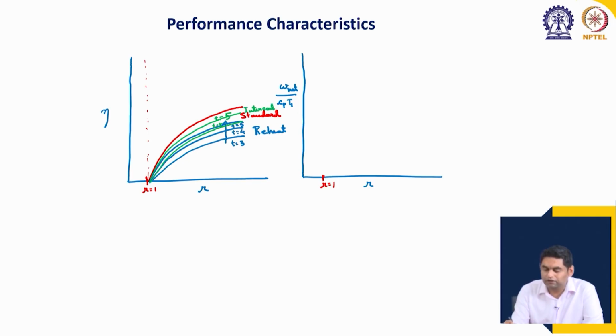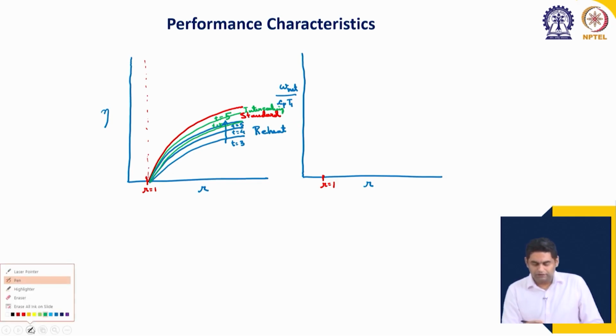When we combine these two, then we get the lowest efficiency, as expected, because both the processes reduce the efficiency, and our purpose of adding reheat and intercooling together is not to improve the efficiency, but to improve the net specific work output. Because we get very low efficiency here, generally these are not used standalone, but regeneration is also added to this, as we will see in the next class, and that makes it a very powerful combination.